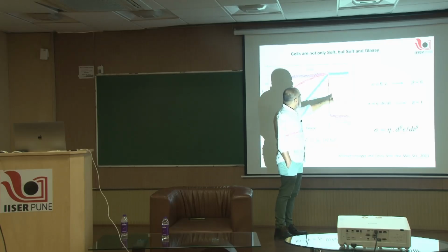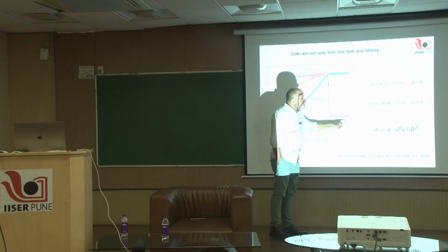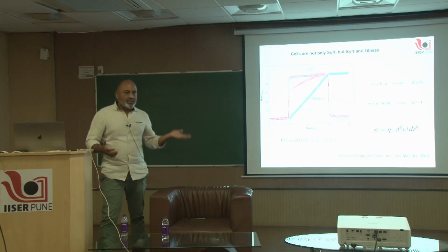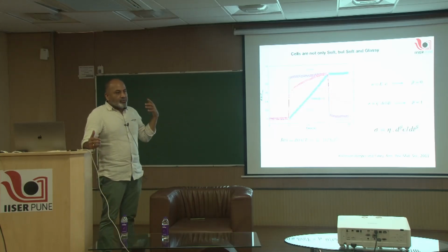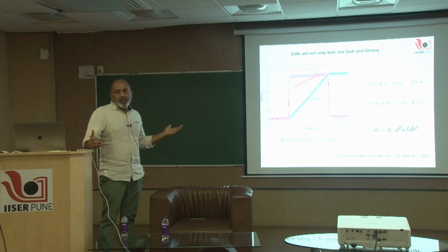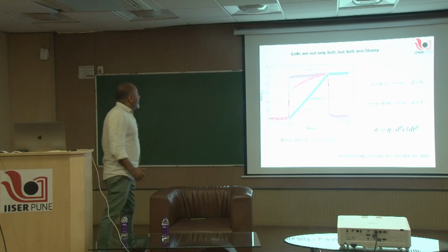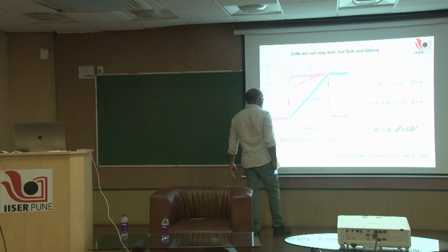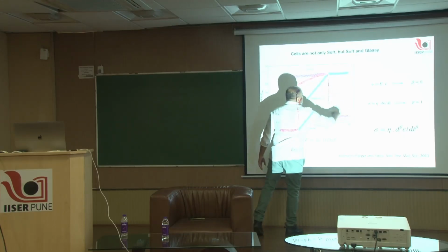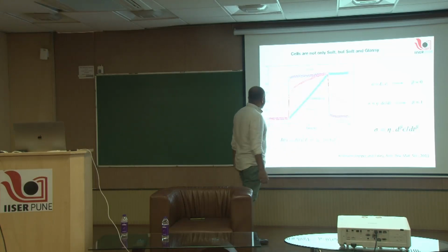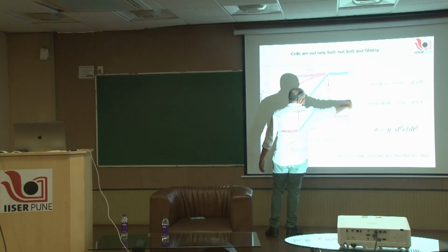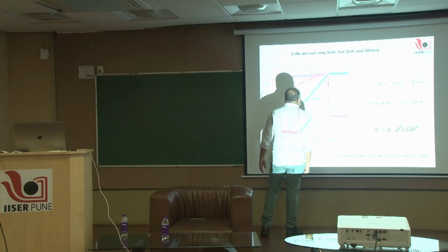But the moment you stop the stress, remove the force, there is some instantaneous recovery, but the recovery is not complete. There will be some part that slowly recovers back with time, and it is never complete. So the part of the material which was elastic has recovered back, and the part which was viscous has not. The way this builds up, the time needed to build this up and the time needed to come to whatever residual strain the material keeps, or plastic deformation one can say, that time evolution